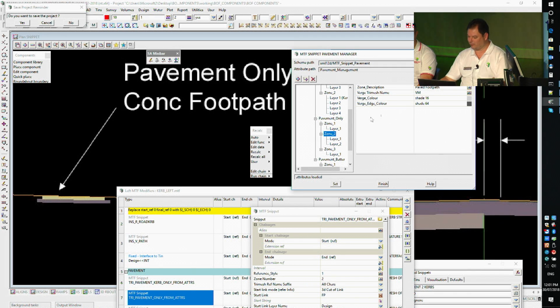So in here, I'm creating a paved footpath. Layer 1 is the pavers, 100 mil thick. Layer 2 is the bedding sand underneath them, that's 150 mil deep. And I've got 100 mil either side of those strings as well being produced. So that's a simple one there.